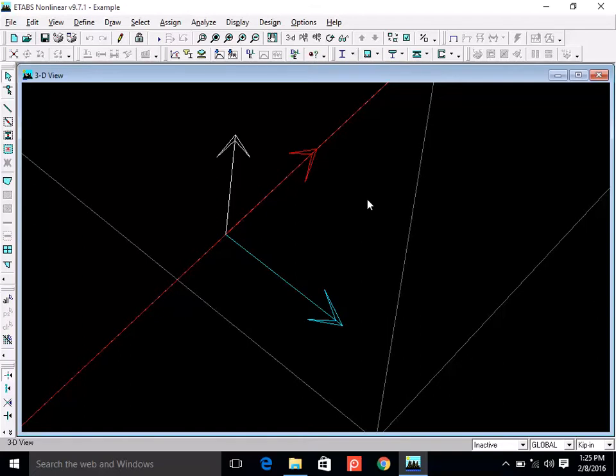So, one is a universal truth, that is, one is always the longitudinal axis. That's not going to change whether it is a beam or it is a column. So if I tell you the direction of two of them, then you can find the direction of the third one. Any two you know, and the third one is very easy to find. So everybody is clear about this axis system for the beams. Now let's talk about columns.